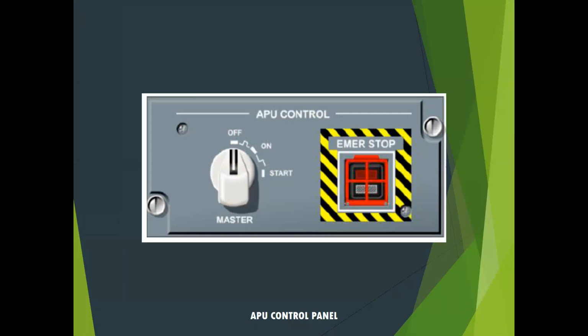It can cause damage to the engine itself in the form of shock cooling and other things like that. So you want to unload an APU in a sequence over time, and that's what the normal control does. But again, if there was an emergency, if someone was going to be hurt by it, or if it caught fire, the emergency stop option allows you to shut it off now.